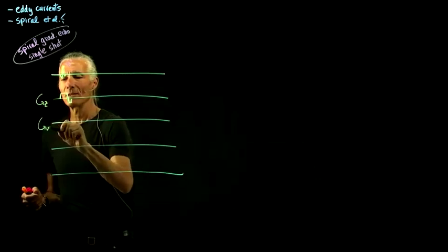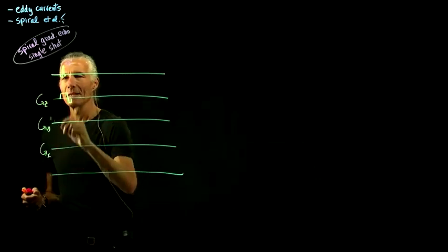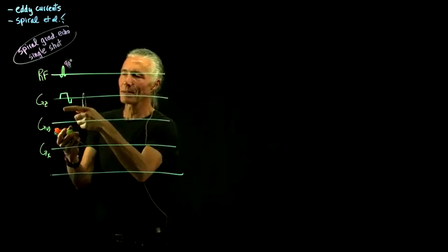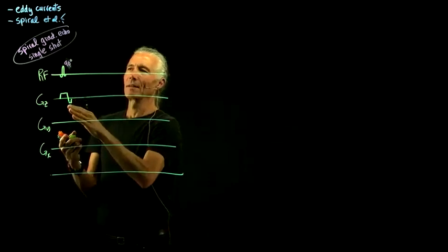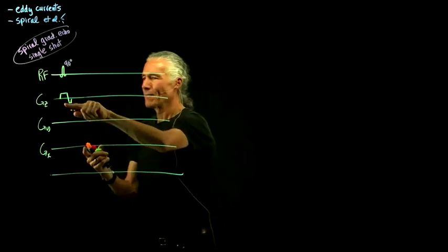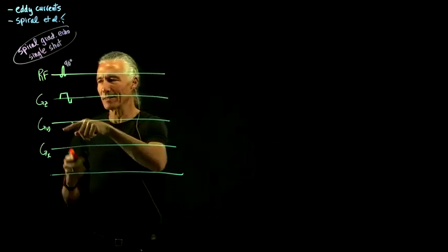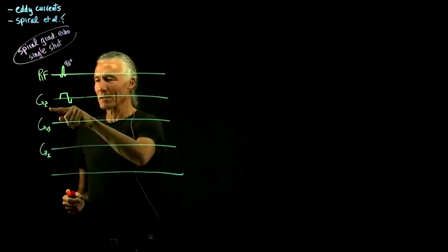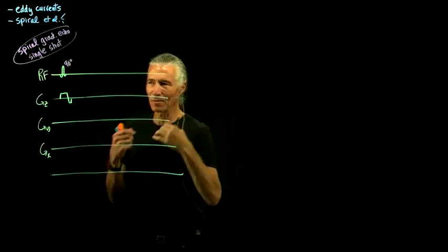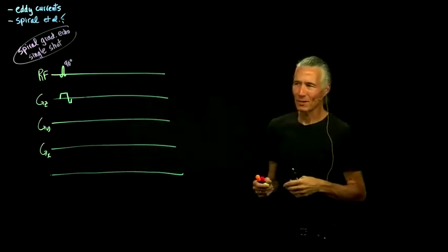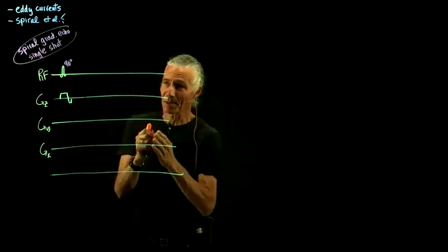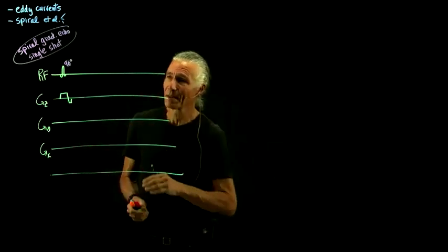So when I write these Gy, Gx, in real life, if you've tilted your slice, you're going to have multiple gradients on. When you're actually running a sequence, the slice select might be spread across several gradients. So writing Gy, Gz, Gx is just a mental way of simplifying that picture, not having to worry about what actually happens when you run a pulse sequence with tilted slices.